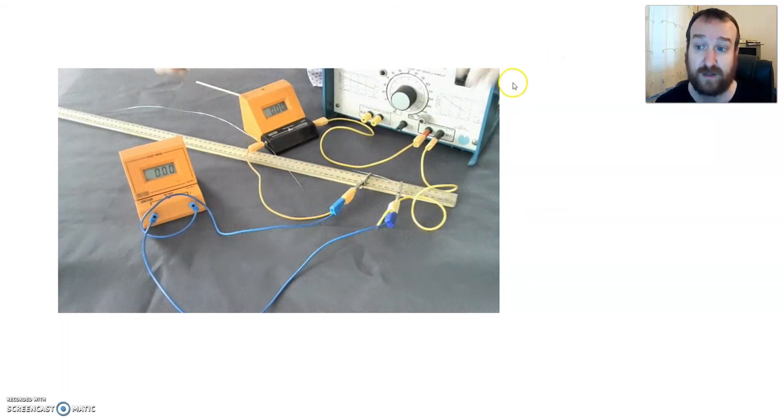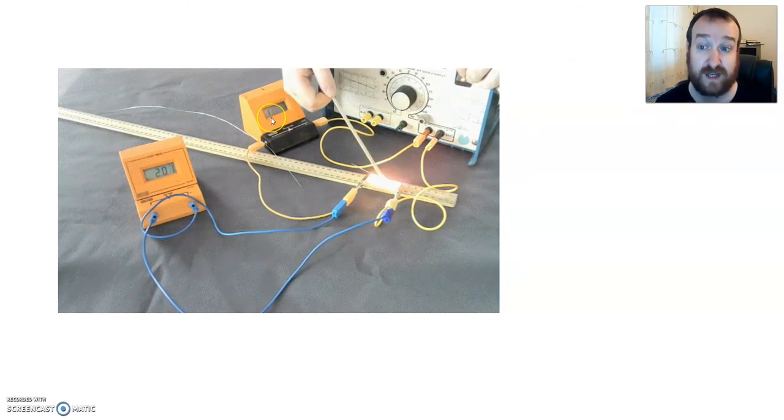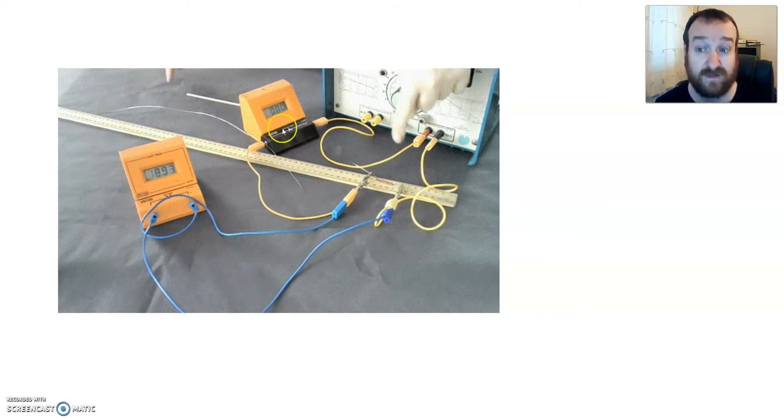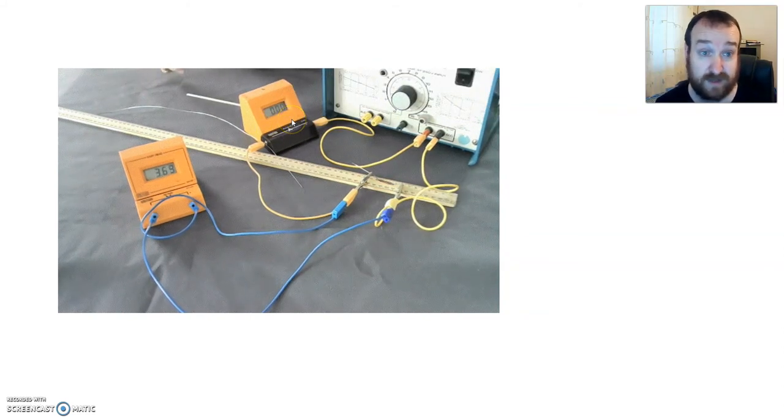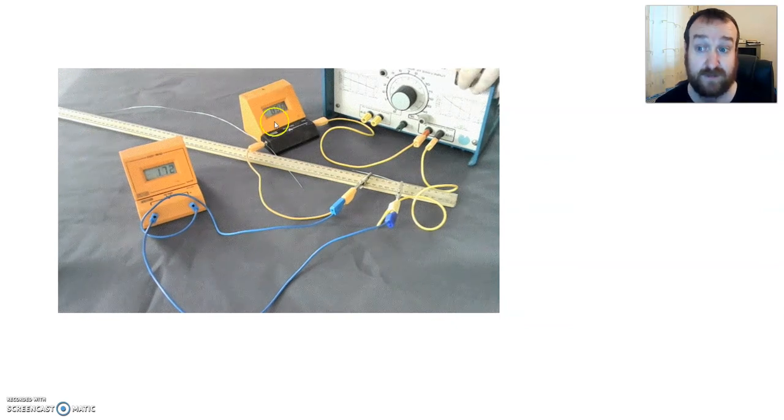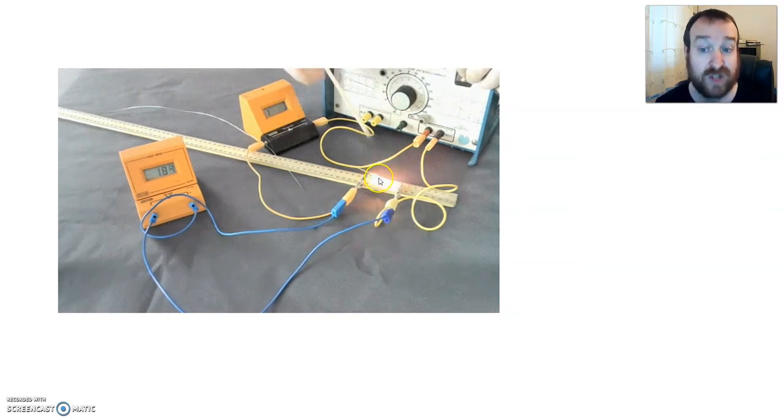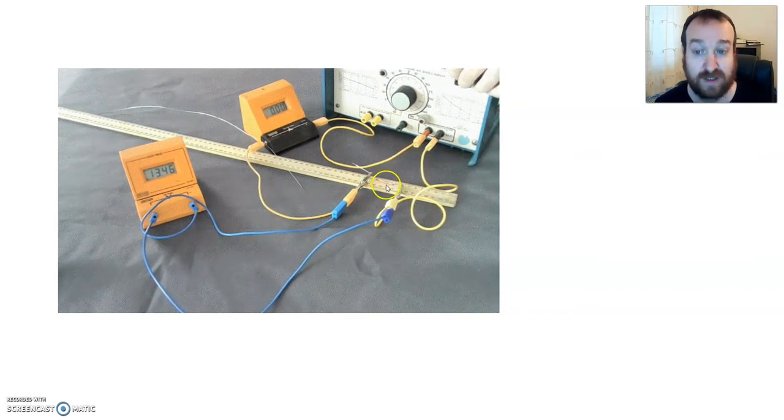The second thing you might notice is the current here. It spikes at 8.5 and then goes off the scale and then goes to 0. So the current was high enough that I couldn't read it with this ammeter. I'd have to have a better ammeter to actually find that real current. And it got so hot that the wire melted and broke the circuit. So this is why this experiment is actually dangerous.